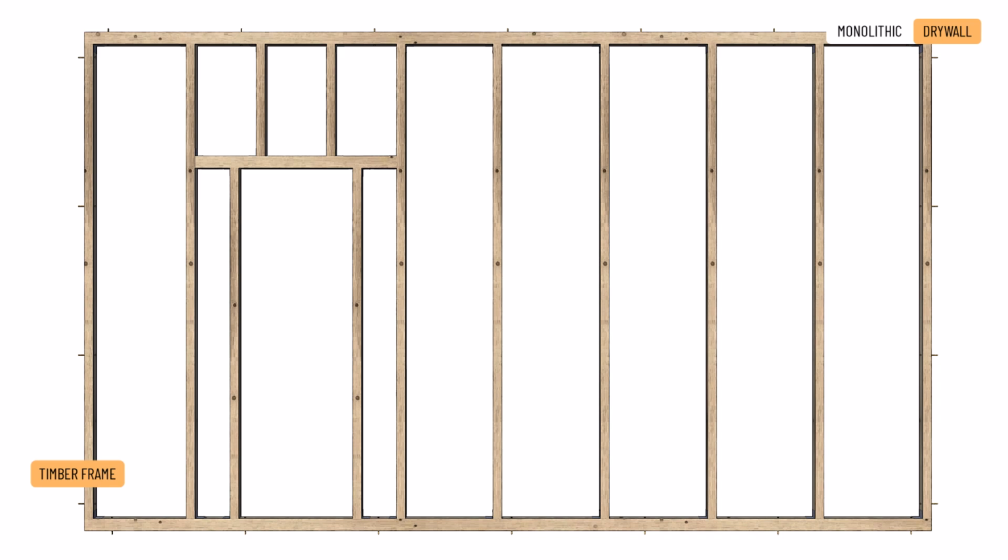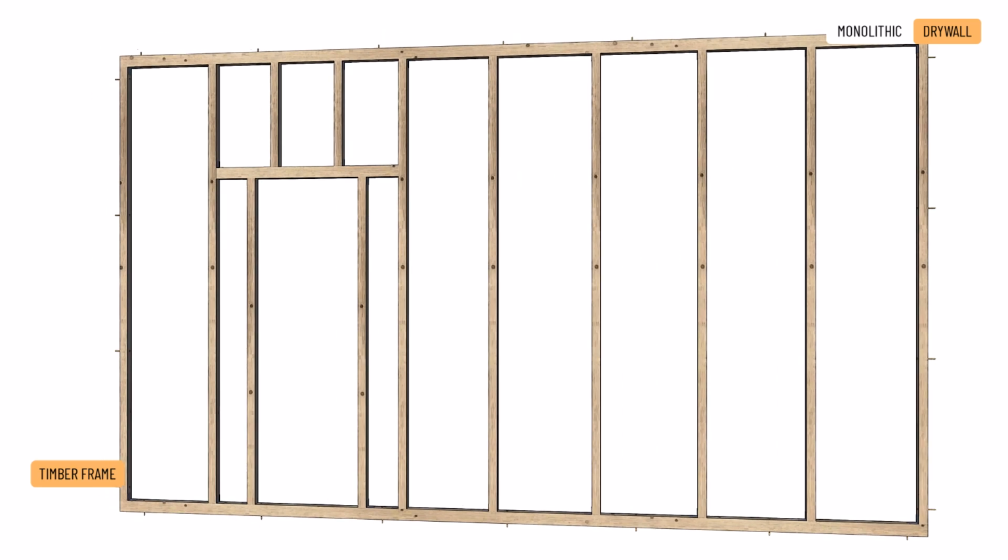The spacing of vertical studs is commonly 50 to 60 centimeters from center. This regular pattern can be broken by the additional studs of the necessary openings, above which a horizontal header is built in as a lintel.